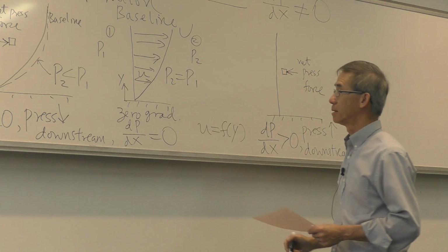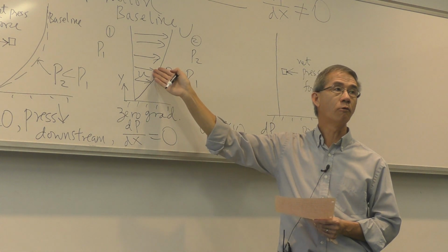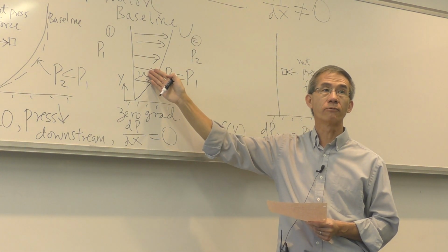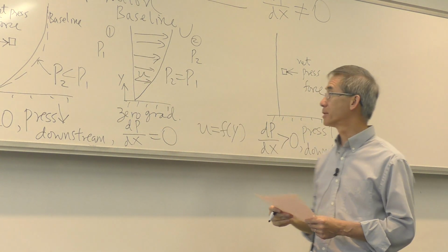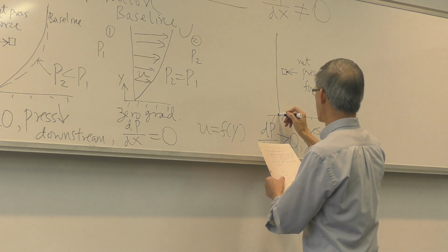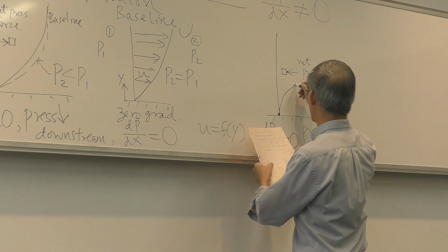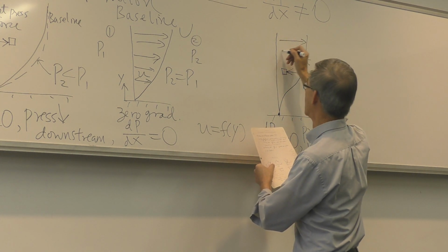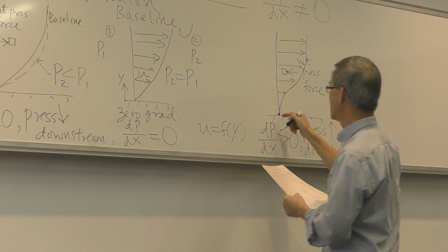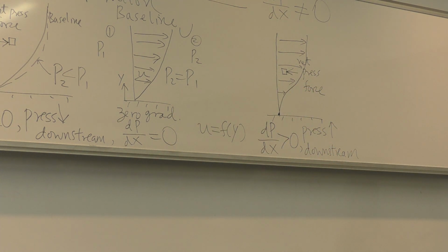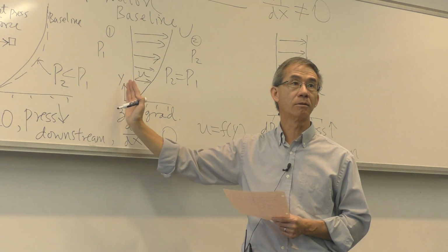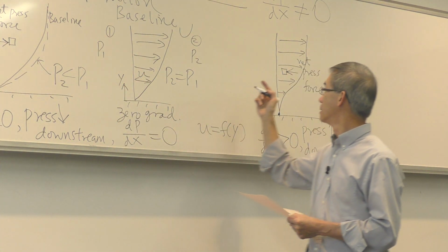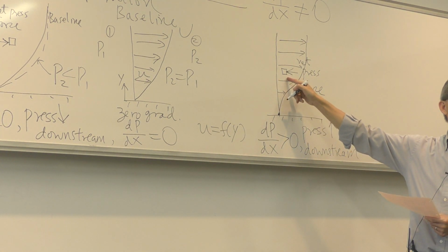As a result of that, this baseline boundary layer profile will be pushed toward which direction? To the left. So I have now all of a sudden a boundary layer that looks rather odd. They look kind of like this, where near the wall I have, in the limiting case, a point of inflection. And the fact this profile is being pushed to the left is simply because of the pressure acting in the direction shown here, which is against my momentum.